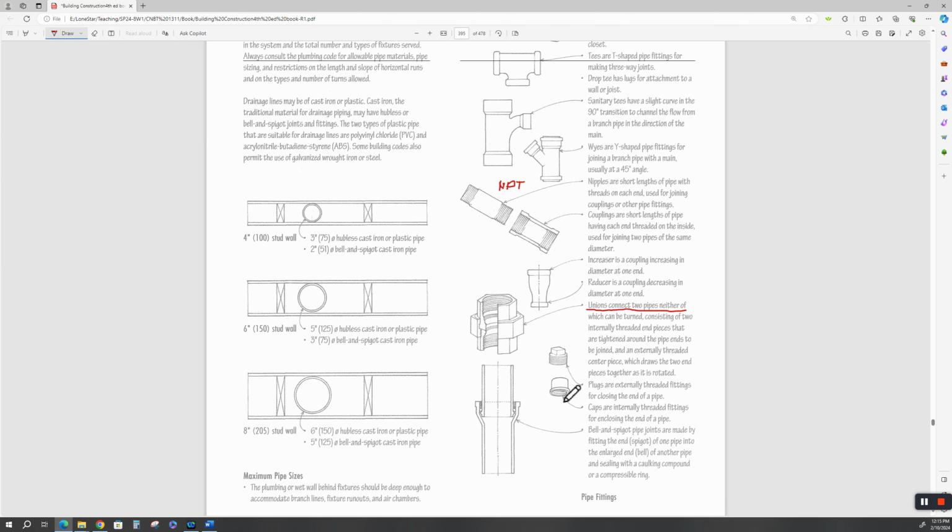These are pipe caps. They go over like a nipple, and it just closes off the pipe. I've got a whole box of these, so when I do plumbing work, I'm not relying on the valves to completely seal, because after long years of service, the valves sometimes don't seal while I'm working underneath the sink or something, so I'll cap them off.